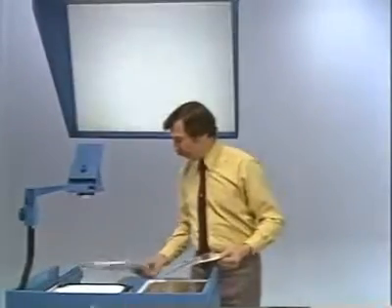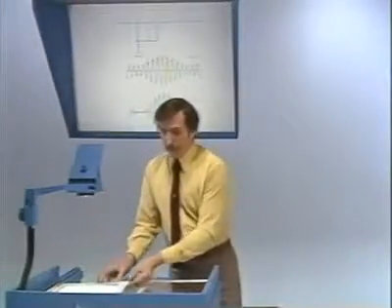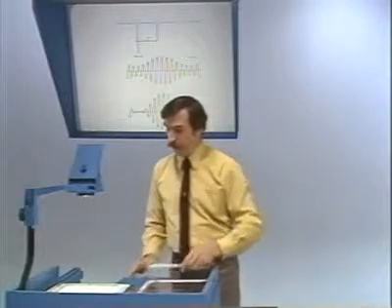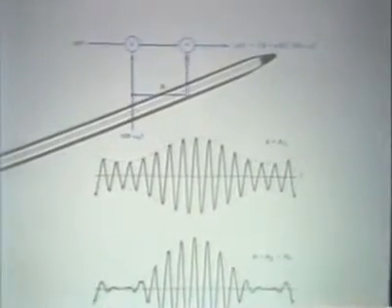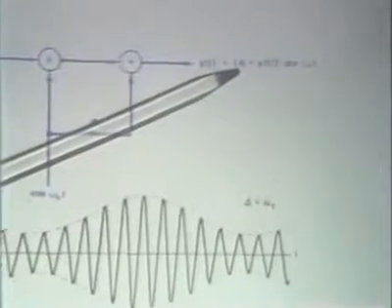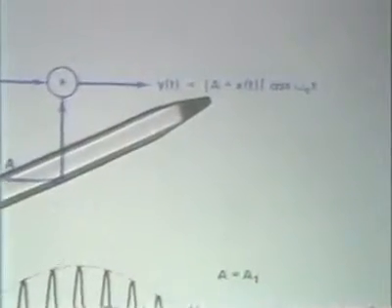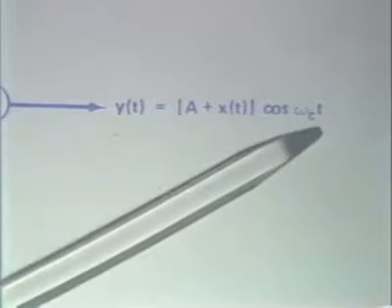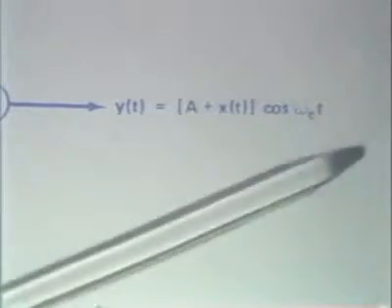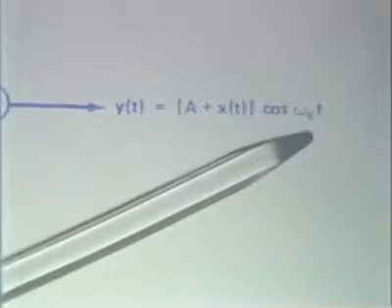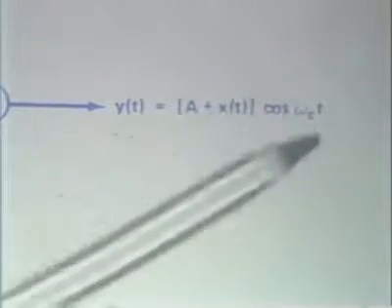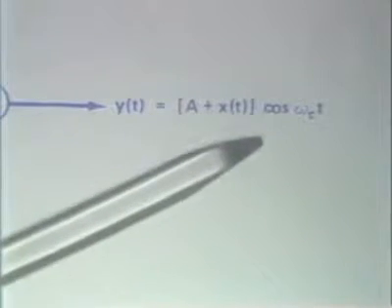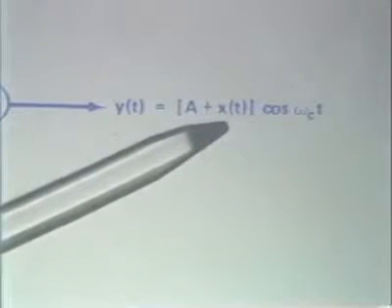What we want to do then, if we're considering asynchronous demodulation, is to take our original signal, x of t, and add to it a constant, where the constant is made large enough so that we're sure that this is a positive signal. And incidentally, let me just draw your attention to the fact that I'm now suppressing the phase on the carrier signal, since the phase is not important to the argument and it's just some additional notation to carry around. Now, so the idea then is add a constant to x of t.